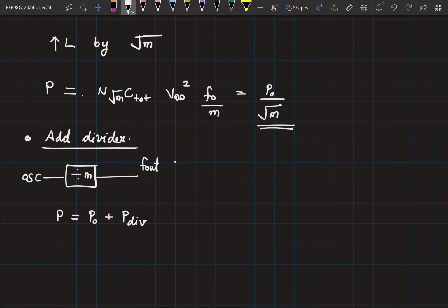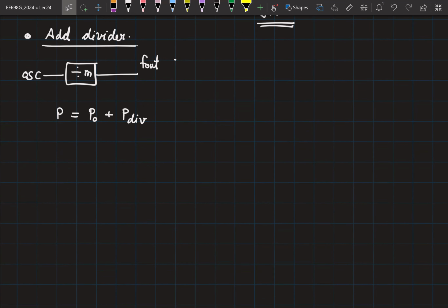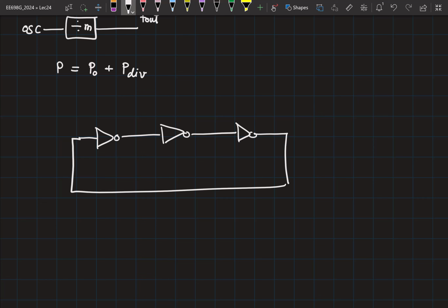Okay, so now before I proceed with analyzing the phase noise of these different circuits, one very quick question. Let's say I had a ring like this, and say I also wanted to make sure that all these phases are separated by equal delay, right? I'm interested in checking all the phases of the ring. So we already said that we will ensure that any load seen by these inverters is going to be equal, right?